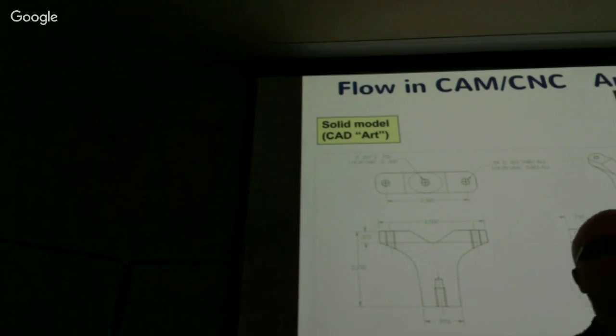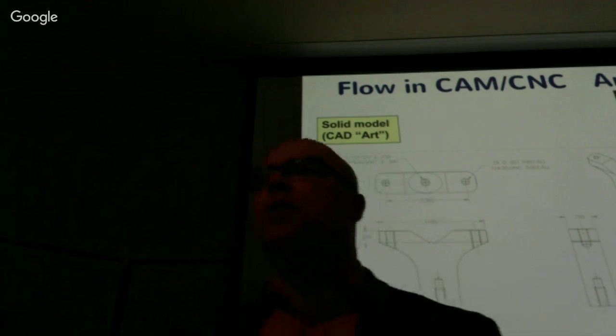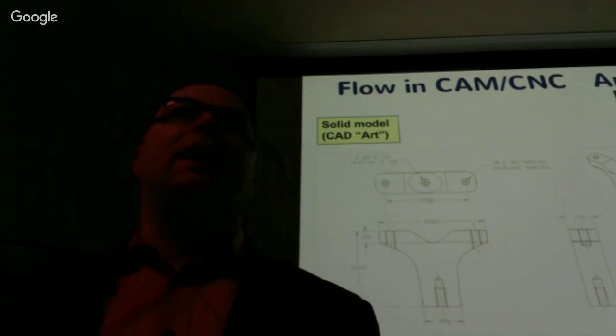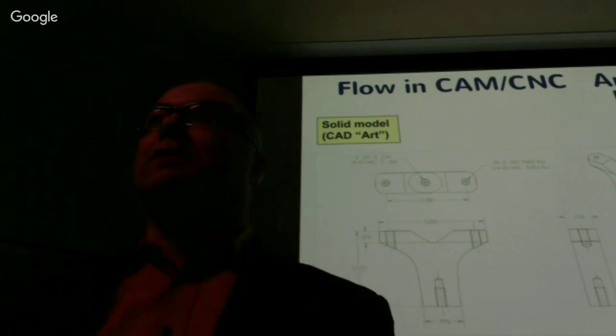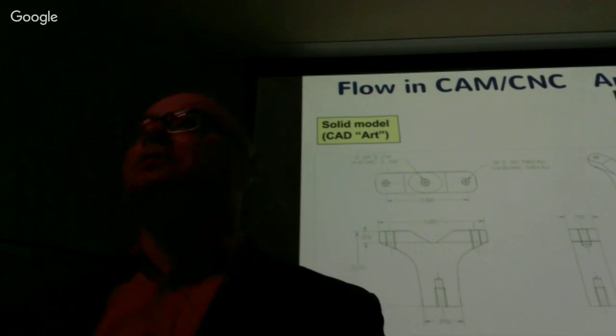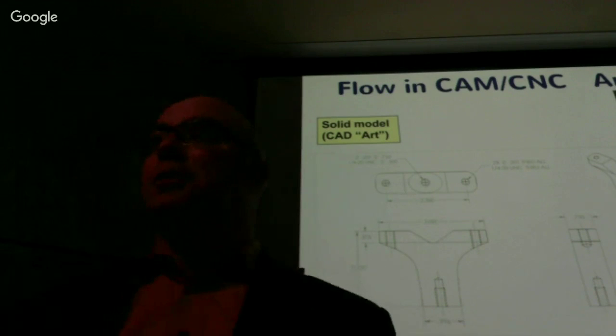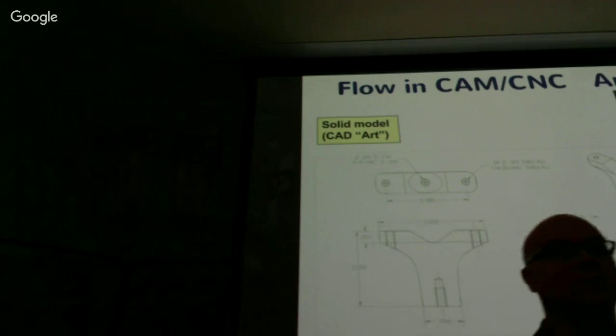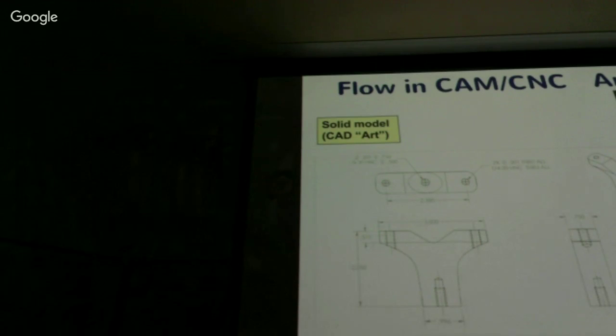I wasn't specific enough. I think it was a 1/4 tapped hole. I wanted 1/4 tapped holes. And so I specified the drill size as 1/4 tap drill, which is fine, except which tap drill you use depends on the threads that you want to make 1/4. Right, so he knew I didn't know anything. You know what they call us when we're fresh out of college and we don't know anything? Kids with CAD. They definitely call us kids with CAD because we know how to draw, right?